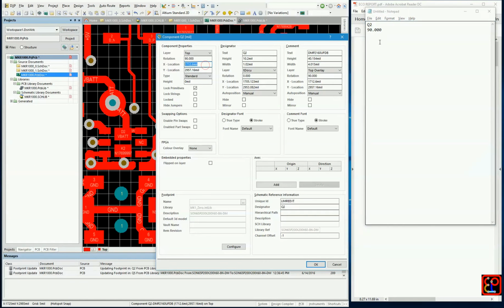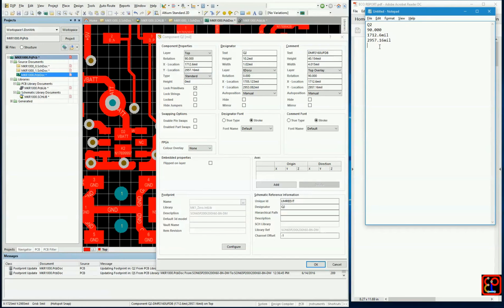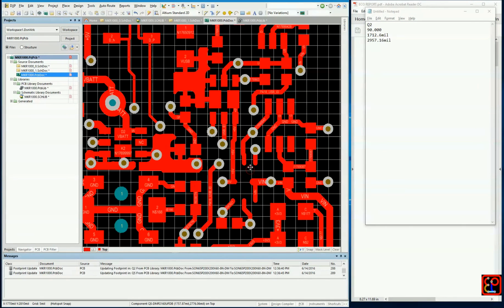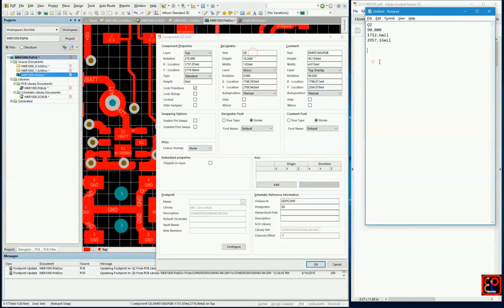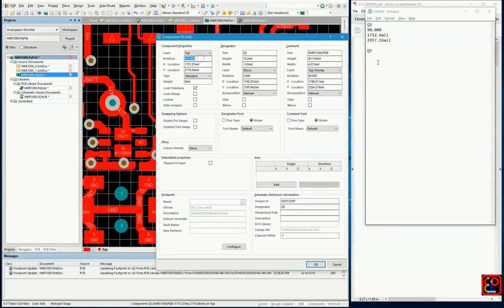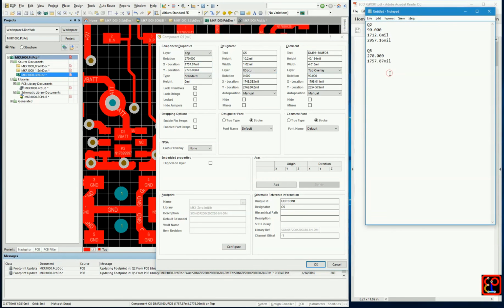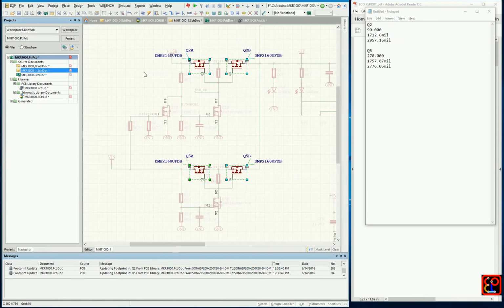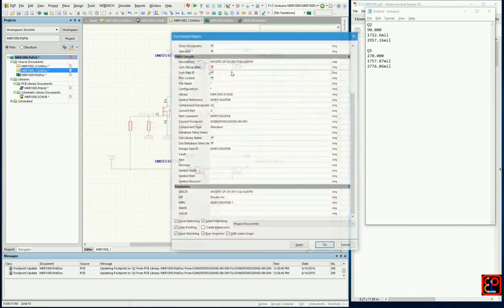As soon as you get all the locations of all the parts, you need to select the part, and in a future step we're gonna transfer the new parts with the new footprint and paste them on the same location. This will allow us to not have to change or modify the layout.